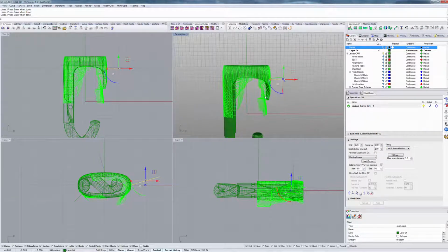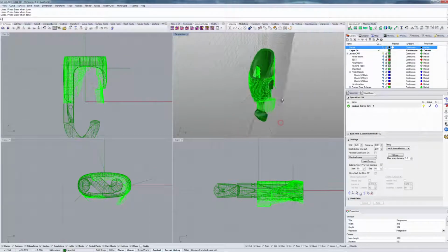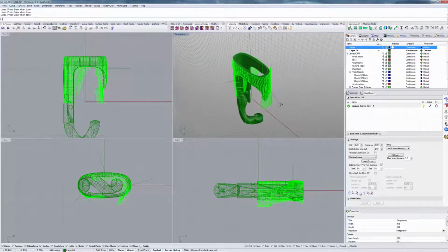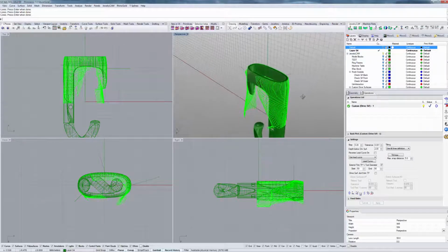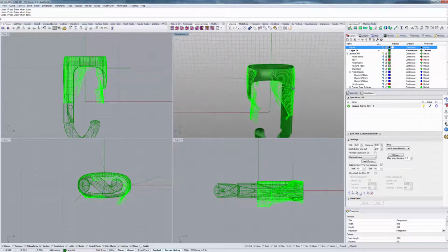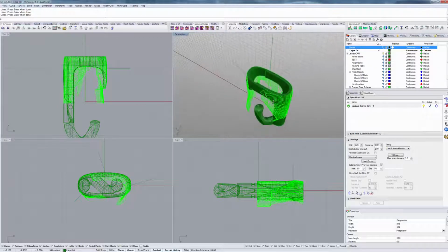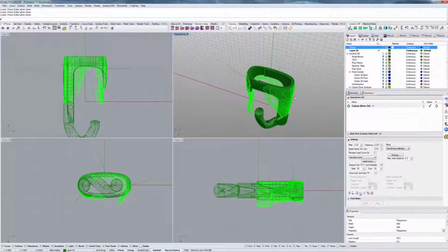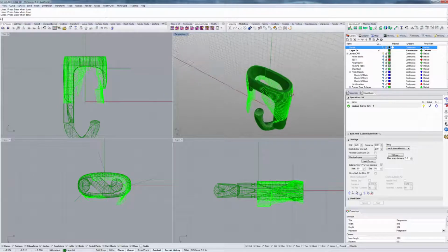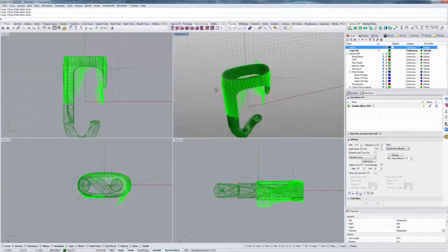We get a somewhat strange diagram of our toolpaths, and that's because we're placing fairly strict constraints on how certain toolpaths are cut as our toolpath is progressing. And as you can see, there are some areas under this definition which it's not able to reach, because now we're in a continuous 5-axis strategy. Between these curves, JewelryCam is trying to find the average of these two tilting angles. So it'll progress slowly from this angle to this angle, for example.